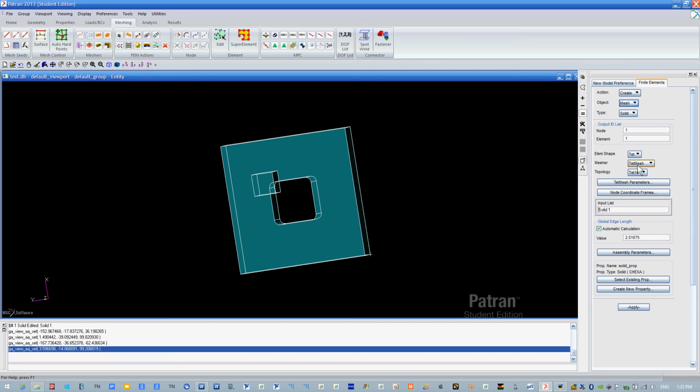One way you can find out if you need more is if you increase the number of elements. We can't really do it with this program because of the limits we have, but if you increase the number of elements and the change between each one keeps getting smaller, then at a certain point, I guess that's how you decide. It's all relative to what you feel is good enough, like in molecular simulation. You step in and say, there's no real benefit to adding any more. I personally don't know. I don't use Nastran Patran all too much, so I'm not sure.